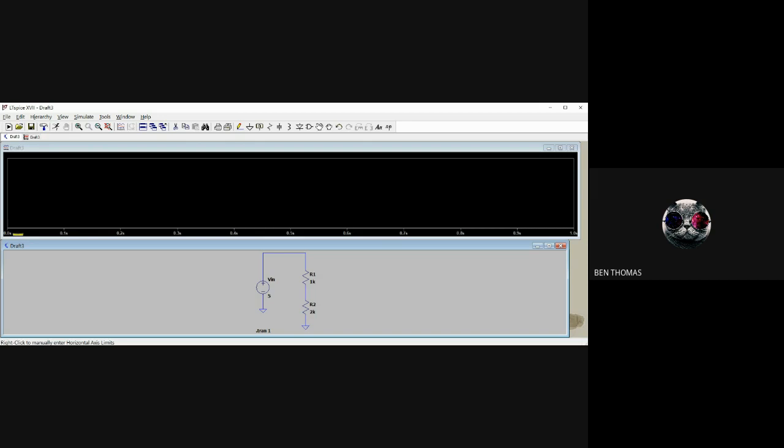We can obtain graphs for this. If we include an inductor, we can see how the current grows from 0 up to the steady state. Transient is used for that, so that we can see what process is happening in the circuit.